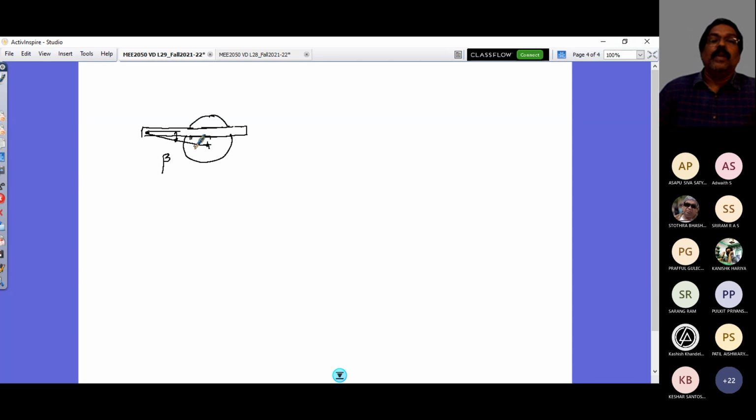And the roll center, or the roll axis, of your solid axle suspension is arbitrary. The axle rolls, so the body rolls as well as the axle. The axle rolls about the roll center, and the sprung mass also rolls about the roll center. The roll center is the point which connects both these masses. That axis of roll of the axle is arbitrary, and it is always assumed to have the same inclination as this trailing arm or leading arm.